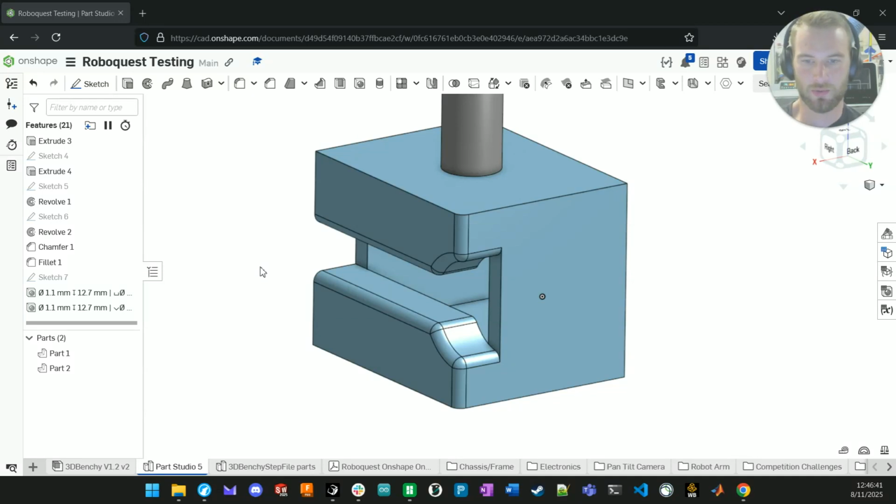All right, so tutorial number 5, we're going to be going over the basic 3D operations, the most important of which is going to be extrude. Extrude is basically what you're always going to use if you're making geometry, either extrude or revolve. You're basically going to make a sketch, and then you're going to use an extrude to either remove material from a part that you already have, or to actually create a part just from nothing from a sketch.